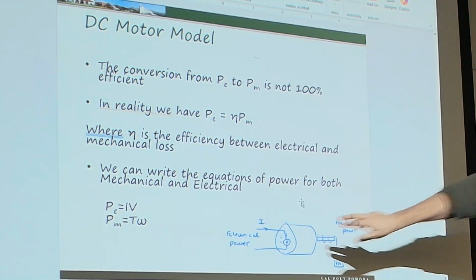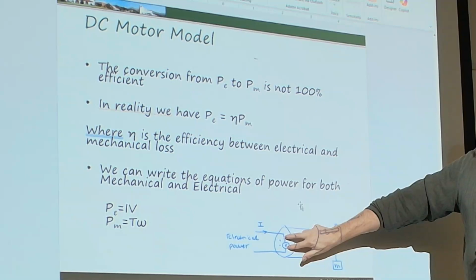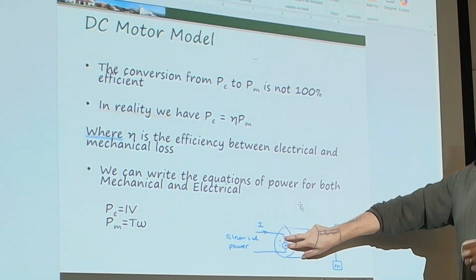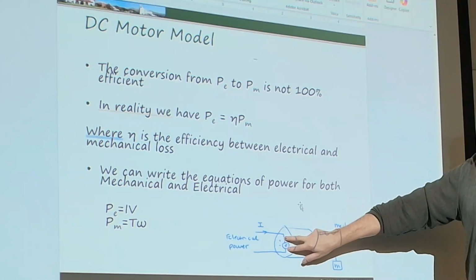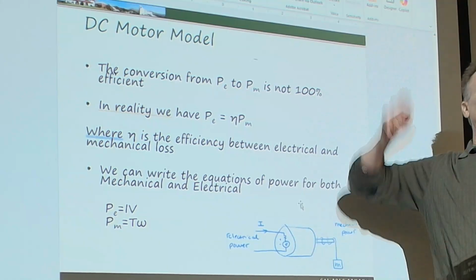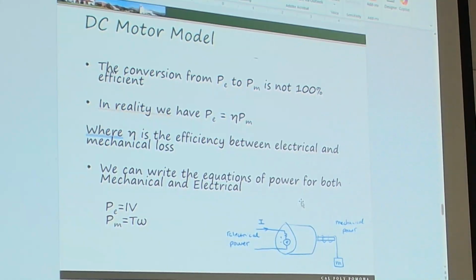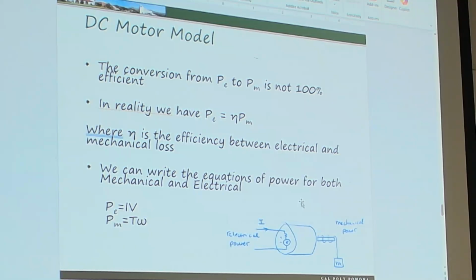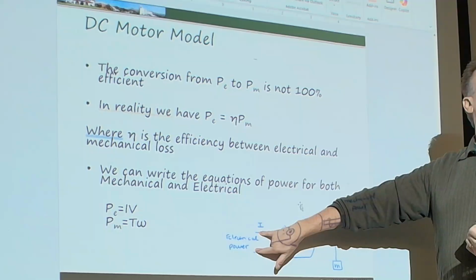So that's what I'm showing right here. That's known as back EMF. Oh, that's what we're talking about in physics. This all in this back EMF. We're like, wait, how did I get there, right? Because this winding's turning. You made it turn, but it's now saying, hey, I'm a wire, I'm turning, I'm gonna induce my own current. Self-induction, right? It's not really self-induction because I've applied the power right here.